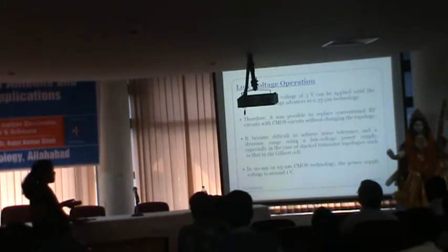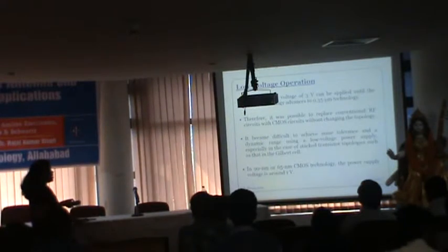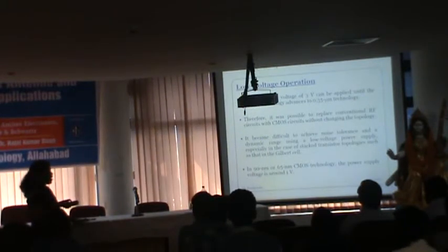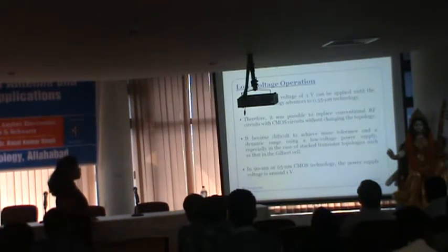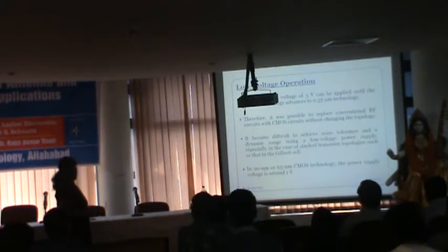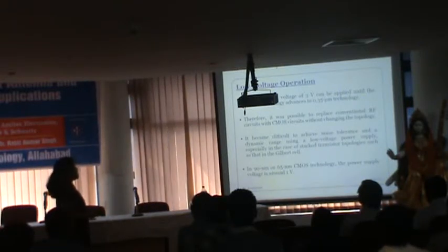It has come already into the market using these CMOS technology. Now the power supply for this is 1 volt. Now the circuit which you are going to design, you should be able to design with the power supply of 1 volt, and that is where the challenge is.